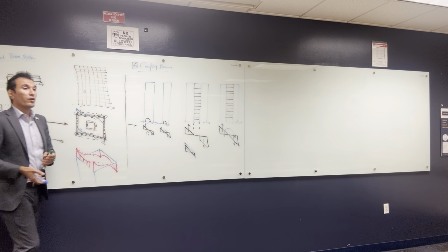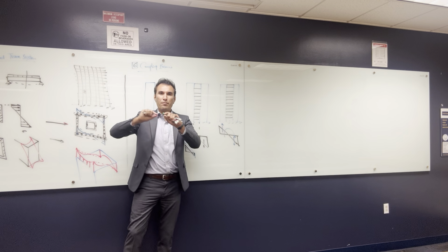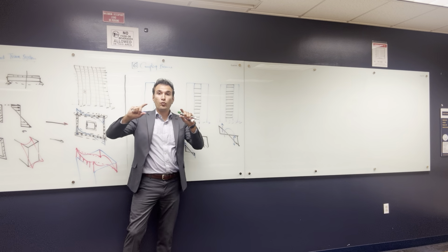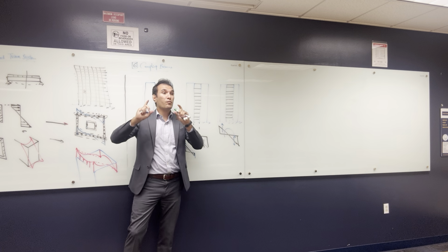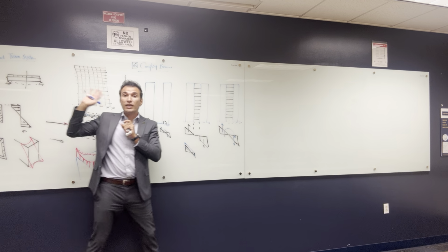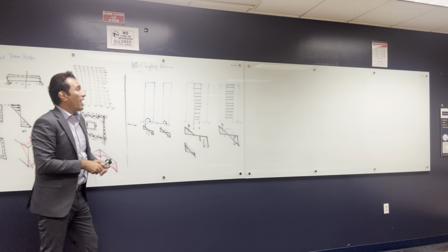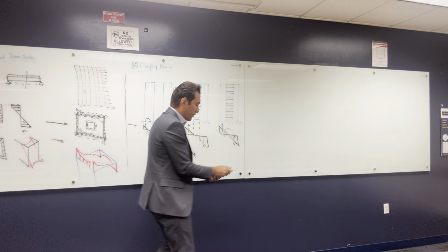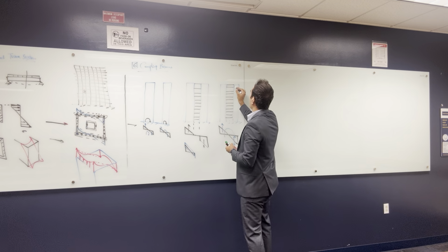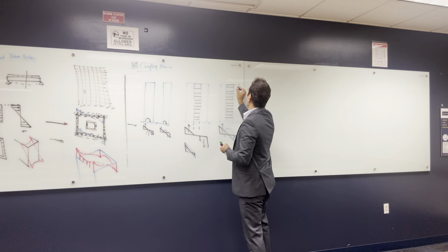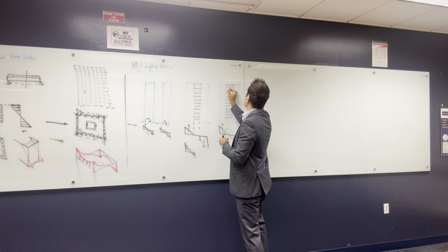That's why, if you remember, when we modeled the beam, we didn't make it as a frame. When we model it at the shear wall location, we make it as a spandrel, with the same cross section as the shear wall, so that ETABS can see it as a coupling beam. And the reinforcement of this beam is different from the other beams. What we usually do is make crossbars, something like this, and this here is going to be something like this. So that's how the reinforcement is, crossbars like this.